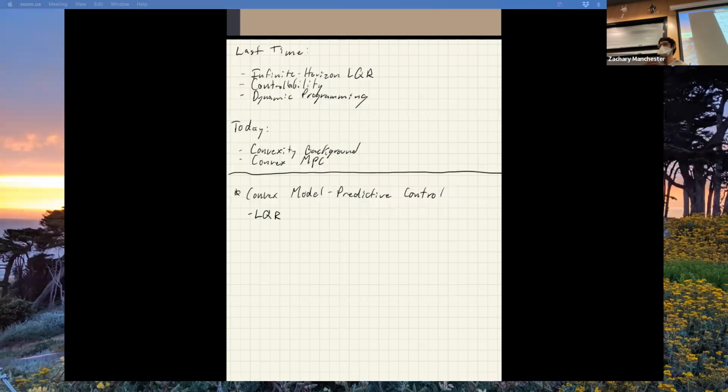It can be applied really well to highly nonlinear systems, actually. So you can use LQR on all kinds of things, super useful. But it assumes that you don't have any constraints on the system. In particular, the most common constraint that you'll deal with in practice where LQR can start to fail on you is when you have torque limits or other actuator limits, like torque or thrust limits. If you're hitting those limits, the controller is not reasoning about them at all. So if you end up saturating your actuators, very often your LQR controller will fail on you. And this is trying to get at that.